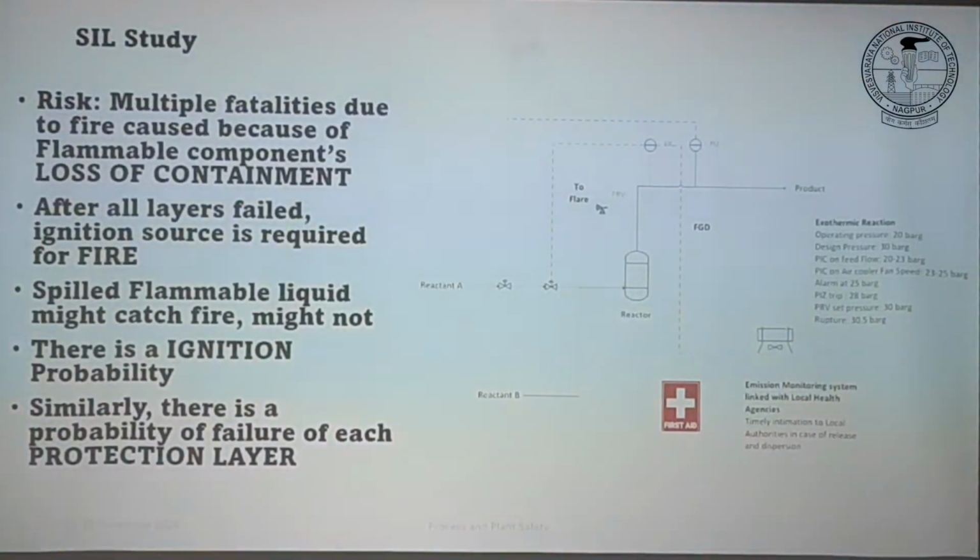First of all, there is a probability of temperature increase or pressure increase. Then on this occasion, you need this pressure loop to act, to sense. So there is a pressure transmitter which is sensing the pressure in the vessel. When pressure is increasing, you need this pressure sensor to act. It must deliver when you need it. So first of all, there is a probability that pressure is increasing, and next, when you need this pressure sensor to work, there is a probability it will fail. Right. If this fails, the next one fails.